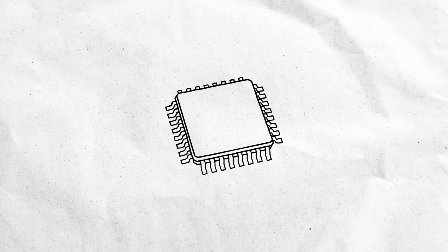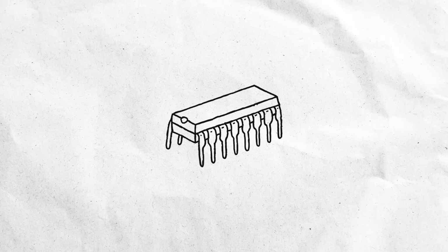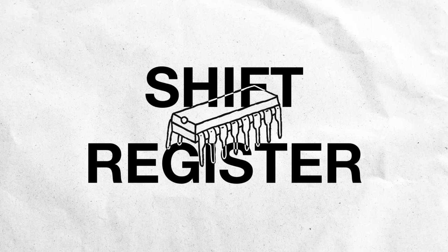Of course, playing our pattern manually is not quite what we're after. We want to design a circuit that plays this pattern for us. But that means we need some way to store it and play it back in a loop. Now, that might sound like a job for a microcontroller, but there's actually a much simpler type of chip that's perfect for this scenario, a shift register.